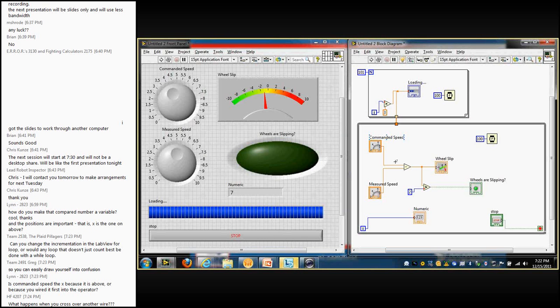What happens when you cross a wire over? If a wire is joined, the dot will appear there. But I can take this wire, for example, and cross over as many different wires as I want, and this won't affect the way that it works at all. If you'll notice, that little junction dot doesn't appear at those locations. It is not connected. Even if you really zoomed in, it creates a little bit of white space, kind of like you would show a highway on a map, to show that those two are not connected at that point.